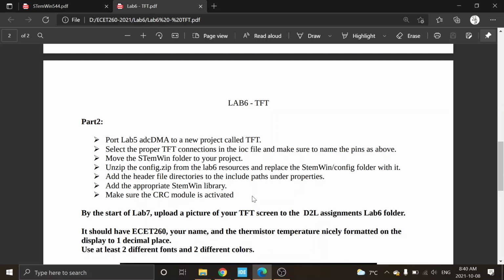So we have all the header files, and if we go to step through our code, it may say it doesn't know where the source code is. That's because there is no source code there. ST didn't pay for you guys to have access to the source code. There's the libraries that you can go use, and there's a big manual for the APIs. And so we need to point to where the library is. And then one of the things with the library is we need to make sure it's in the right format that our IDE is going to want.